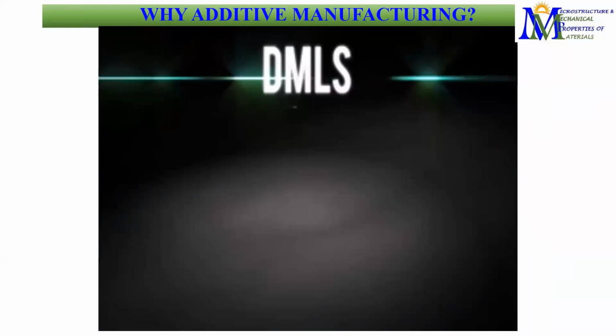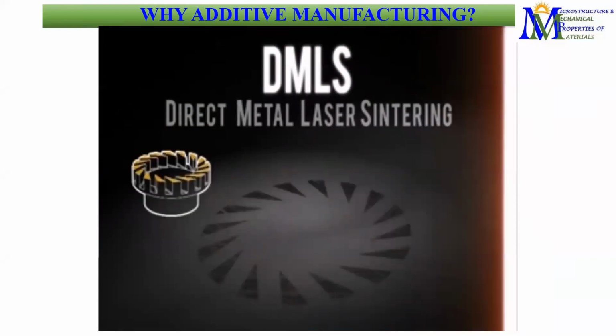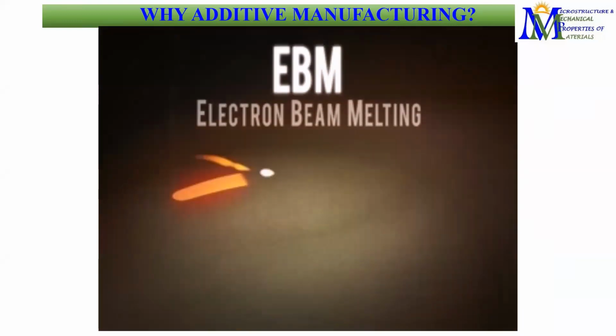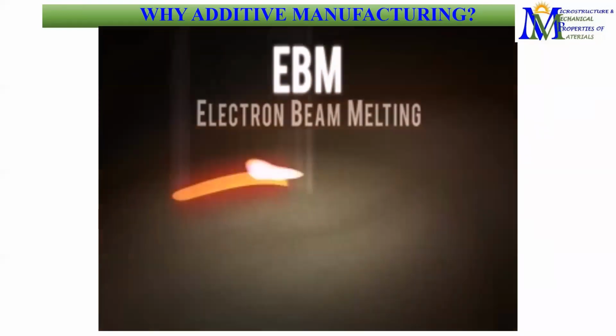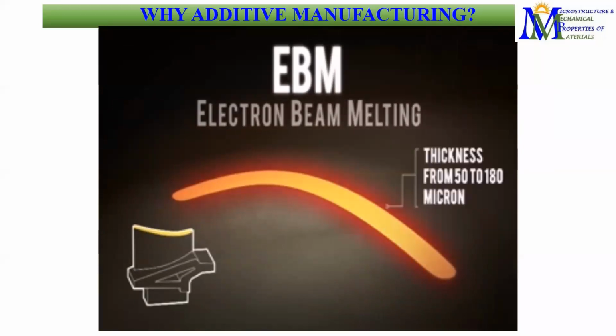DMLS, direct metal laser sintering, is the most diffused and enables the working of many materials, using a laser beam to melt the material into the form foreseen. EBM, electron beam melting, sees Avio Aero as undisputed leader and the major expert worldwide in the manufacturing process applied to TAL. In this case, an electron beam is used in the melting process of the material.